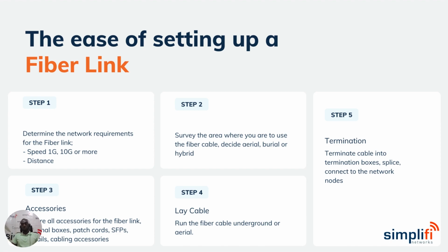You also want to know the distance. So if you can identify two points that you want to run fiber between, you want to know the distance between those so that you can know how much fiber you need. Then secondly, you typically would have to do a survey, that is, study the environment where you want to run fiber.